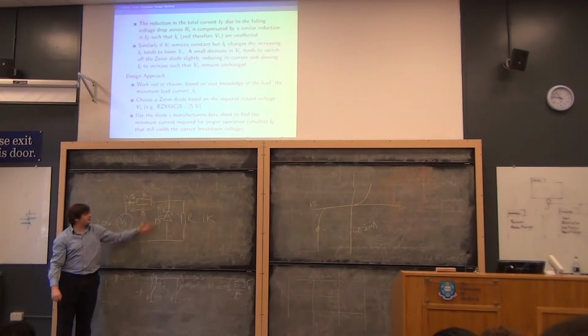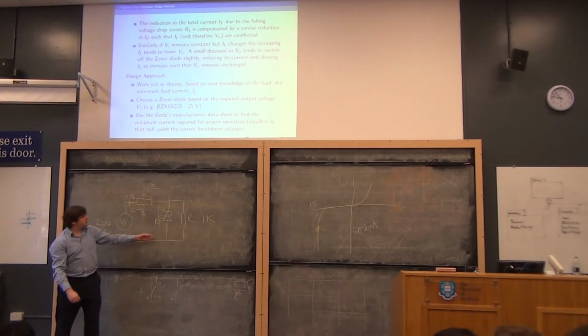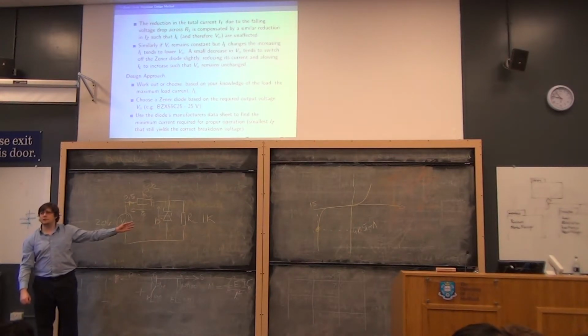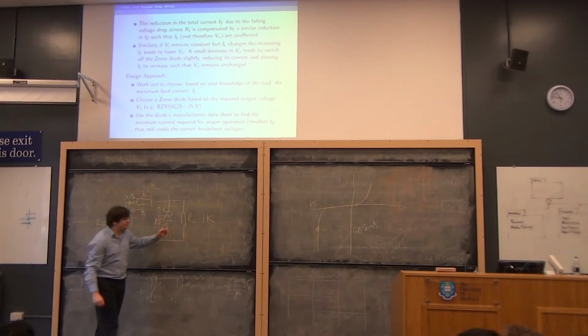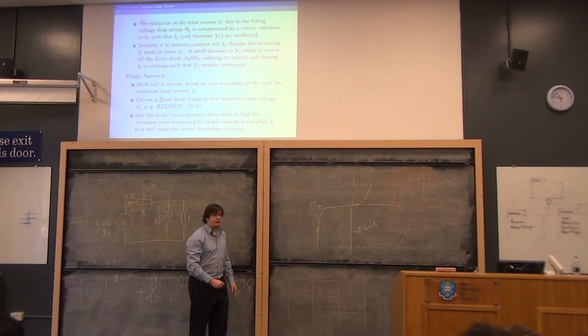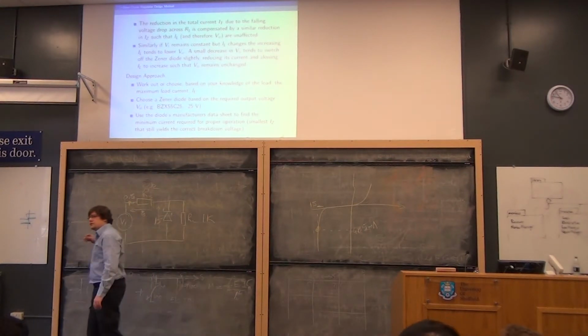So when we say it's 15, we'll be saying, oh, well, there's still 15 milliamps in here. So there's still 485 milliamps in the Zener diode. That isn't going to be true because we will have moved slightly that way along the curve. And there will be slightly more current in the Zener diode, and there'll be slightly less current in the resistor.